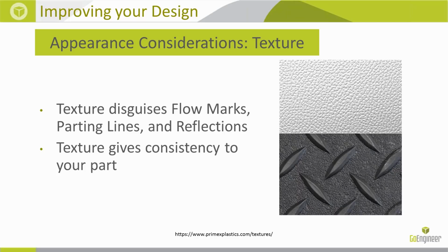So once you cut the mold, and once you've decided that your part is exactly the way you want, you've done your prototype, you've done your first part out of the mold, you've done some analysis and you're happy with that part, texture is a secondary operation. So what they do is they go into the cavity and they apply that texture so that when molten material flows in there, it comes out with that texture. So it's really important that your design is finalized, because any rework done to the mold, then you also have to retexture it. And that is an added cost and more time.